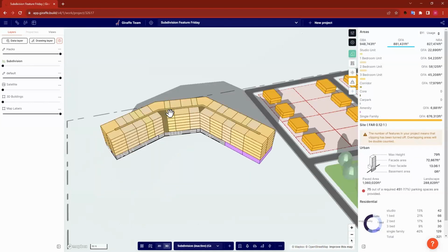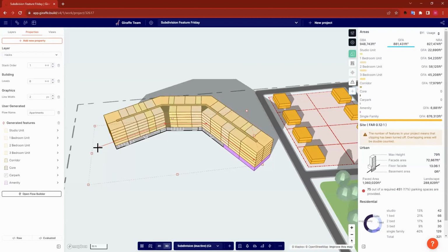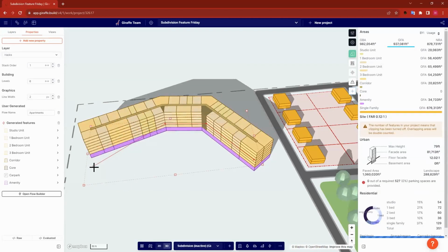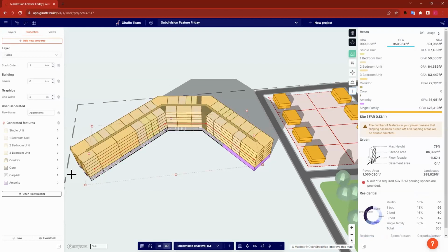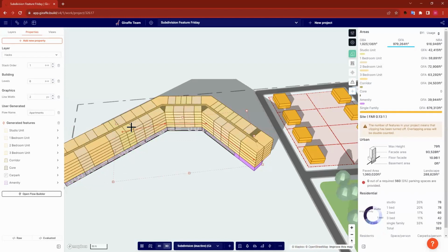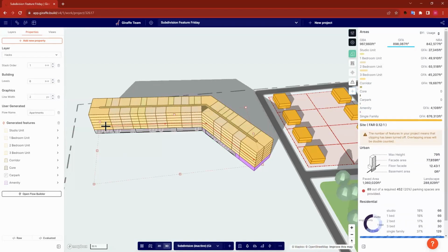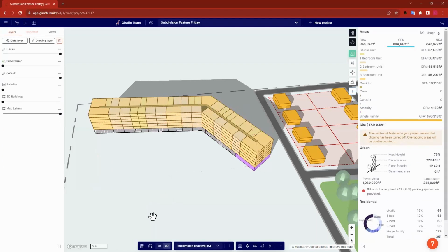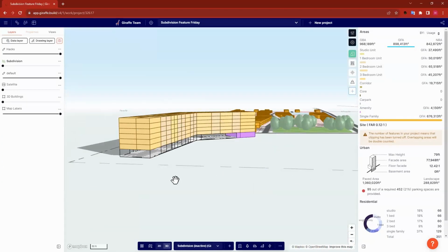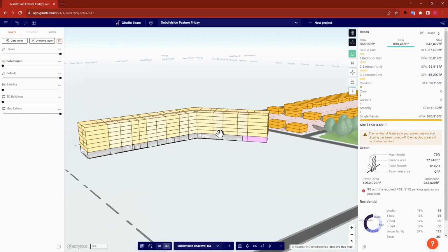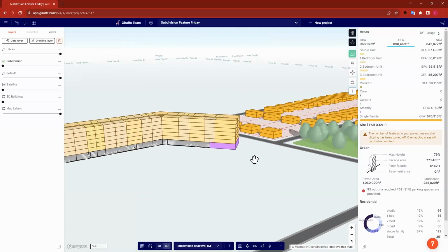And then what's nice about that is as I change the size and shape of this building, it automatically fills in with that mix of amenity and car park as needed. So rather than having to draw those shapes manually, individually underneath the apartment algorithm, you can just edit that one single line over and over again and have those updates made as you go.